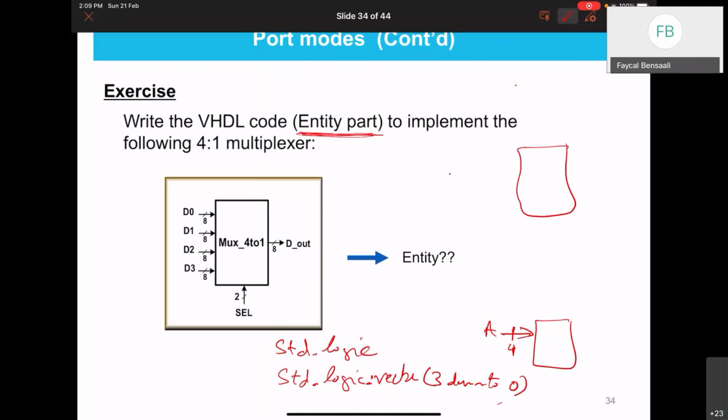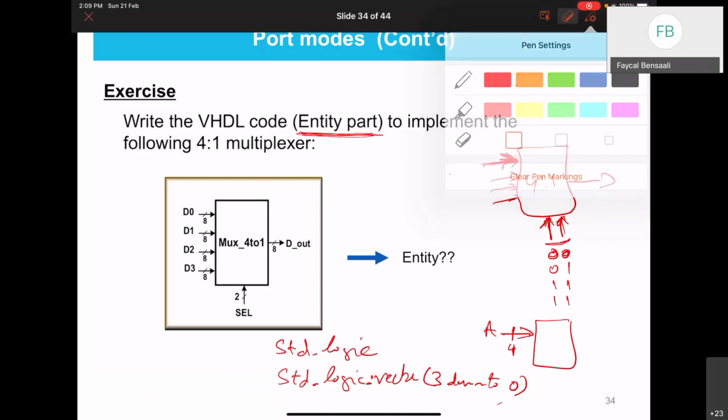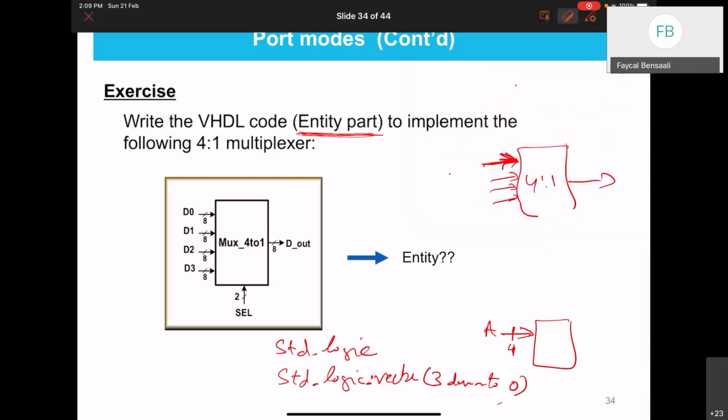You know the normal multiplexer. If you have 4 lines here, you have 2 control lines. We have 1 output. This is a 4-to-1 multiplexer, right? Those 2 lines are together. If it's 0, 0, we get the first line out. If it's 0, 1, 1, 0, 1, 1. So when we declare this in VHDL, it's basically one bus of 2 lines. So we put it as 2, and this is S, the select line, or whatever name you want. So this is 2 lines, and basically we use STD logic vector for this one.